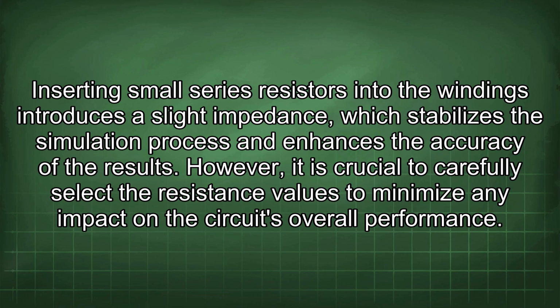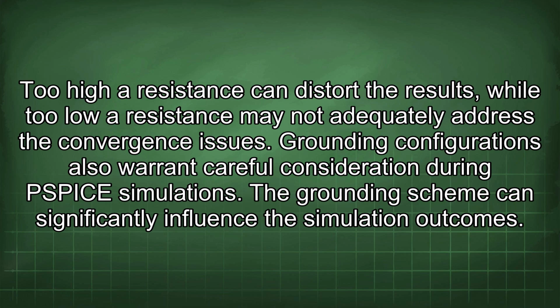However, it is crucial to carefully select the resistance values to minimize any impact on the circuit's overall performance. Too high a resistance can distort the results, while too low a resistance may not adequately address the convergence issues. Grounding configurations also warrant careful consideration during PSPICE simulations.